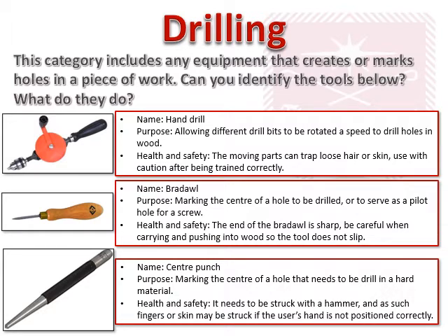The bradawl, we can use that to push into a piece of wood to mark a hole or to serve as a pilot hole for a screw when you're screwing a fixing in. Obviously it's sharp, so we need to be careful when we carry it around and when we use it so we don't slip.